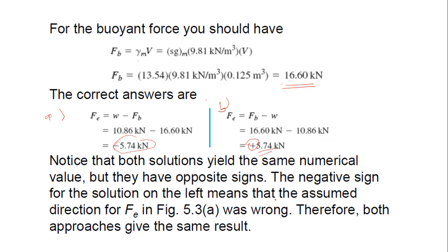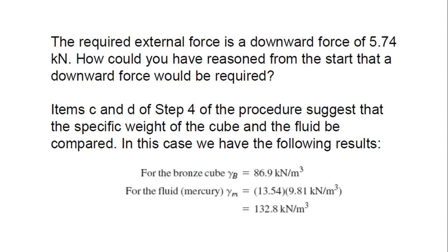You have to do these steps whenever you want to answer the question. It's not that you can follow, you have to do it. It's a must. You have to show your calculation, your step by step, how you determine the direction of the force using the value that you have calculated. But just as a trick, you can always determine whether the force should be upward or downward by comparing the density of the object and the density of the fluid that it is immersed in. Okay, so that's how you do it.